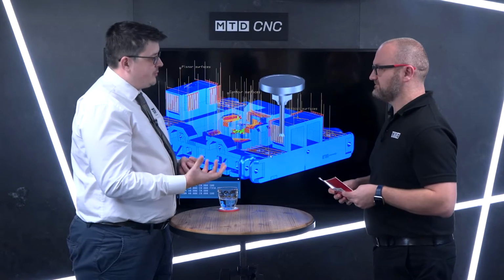If we have a situation such as producing an M14 hole, where your biggest drill is a 10mm drill, Tebis will know that it can use the 10mm drill to take out the material, then come in and remachine using an end mill before it taps. Wow. Using true automation. True automation.